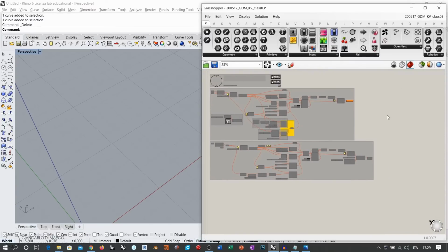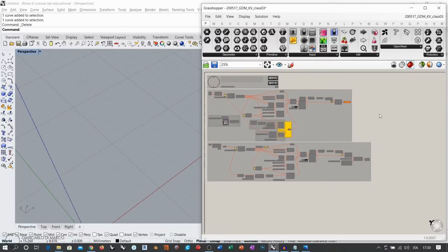Now, in order for this algorithm to be implemented, you must install a plugin which is called Plankton, and it gives you access to this kind of primitives here, which is the Plankton mesh, and it represents a list of 3D n-dimensional half-edge meshes.